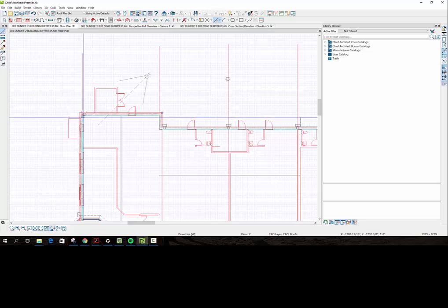All right, now we want the water to come up. It's coming up, and we're going to have a high point in the middle this way. Let's get a high point in the middle this way, or we can even, just to keep it simple, put the high point on the high point of that guy there. All right, which is right there.